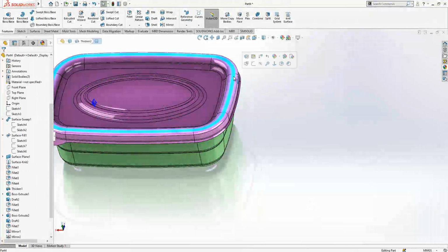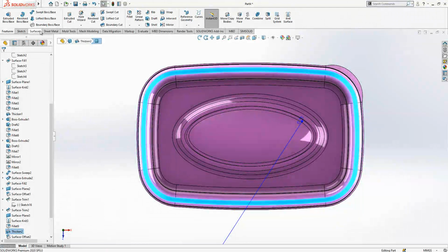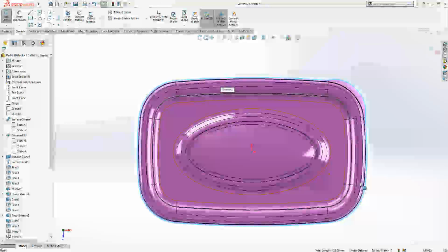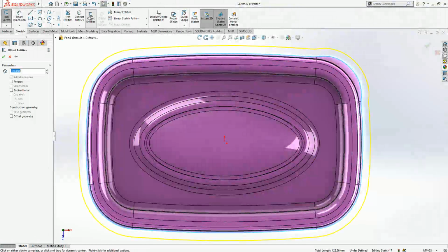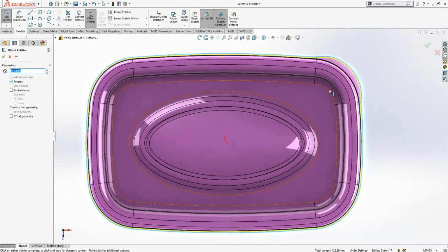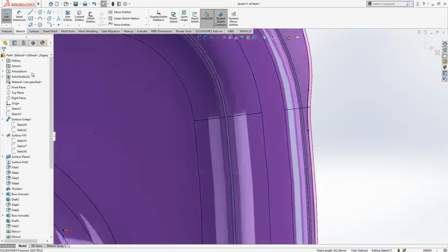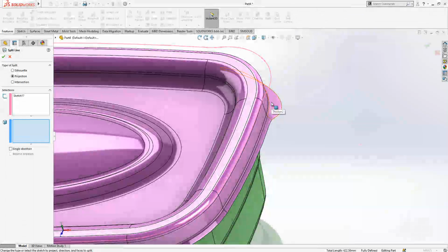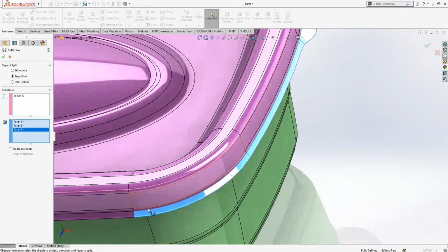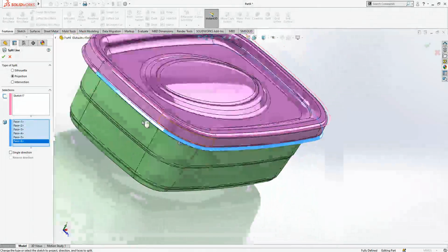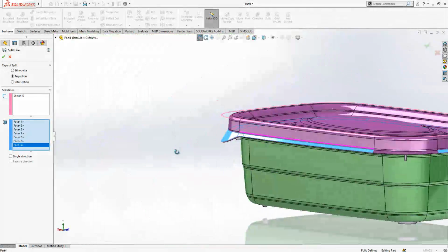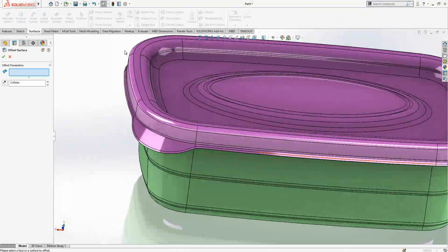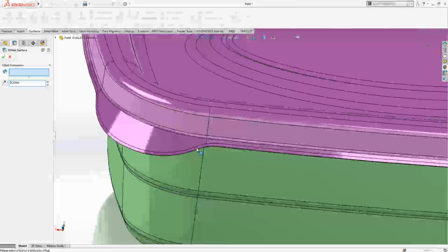We look from the top plane here, guys, and I will create a sketch here. And I want to create a nice edge on our cap. Offset entities inwards 0.3, 0.35, sorry. And then I will create a splitting tool, which is a very nice tool, split. This one. All outer surfaces of the cap, in fact, especially this one. Yes, created. Now what we do, we go to surfaces, offset surface, 0.2, and I select this